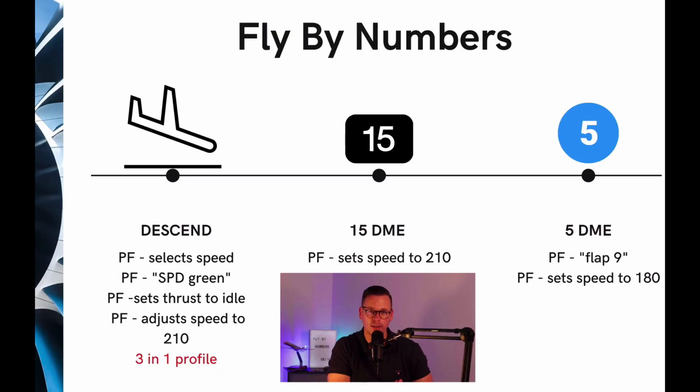When it becomes time to descend, of course we want to make sure that we can actually land at Cape Town, so we need to check the weather, we need to set the aircraft up with the applicable speeds, and we do that by putting the speeds in the multifunction display. That's explained in another exercise. But in other words, we need to make sure the aircraft is set up. We also have to brief correctly, paying special attention to the environment, any restrictions that you might have, and the weather. We also look at fuel.